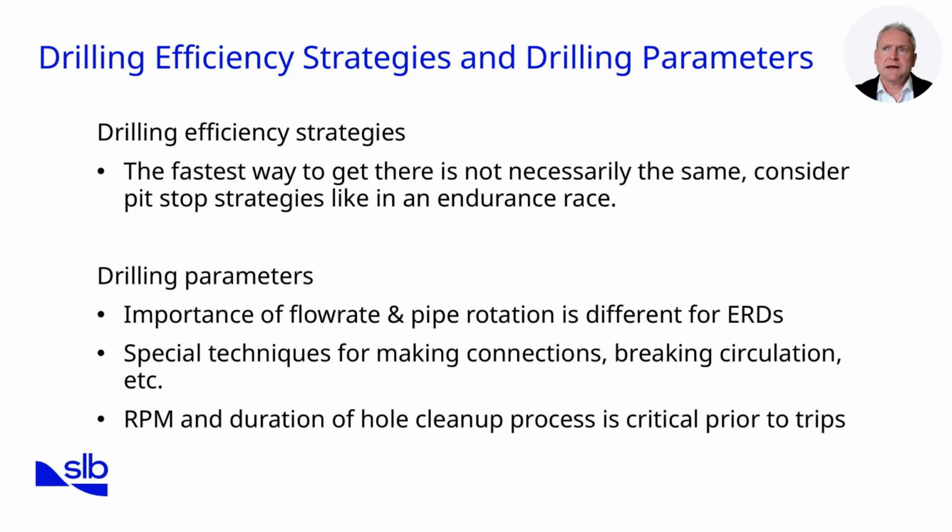Drilling parameters in ERD must be approached differently. Flow rate and pipe rotation are both critical, but their relative importance shifts compared to vertical wells. Maintaining circulation helps clean the hole, while rotation assists with cuttings transport along the low side. We also use special techniques for connections and breaking circulation, as these points are particularly vulnerable to stuck pipe or cuttings settling. Likewise, RPM and the duration of hole cleanups before trips are critical.